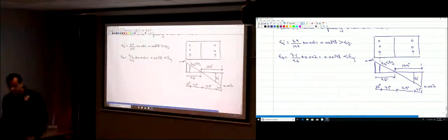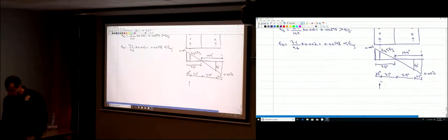This part of the concrete is under compression, okay? So we have three forces. We have a tensile force in the steel. How much is the tensile force in the steel? It's F yield times area steel if the tensile steel yielded. It didn't yield, so it's Fs times area steel. You need to find Fs.